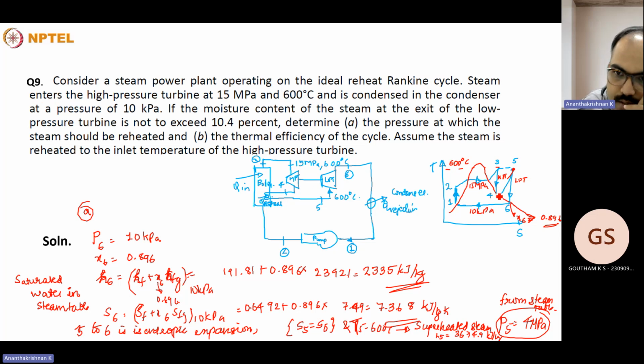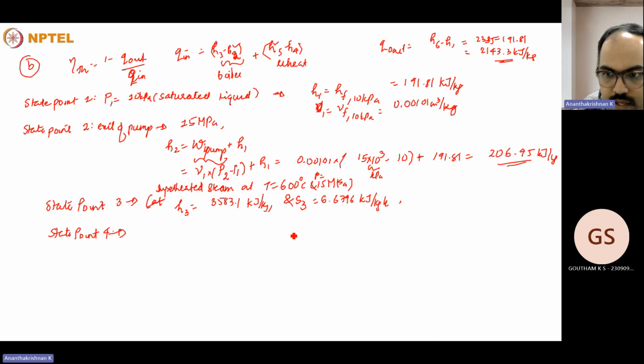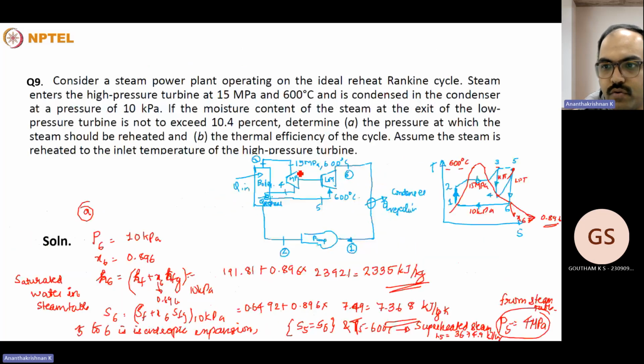So there are two particular cases. Take the case when it is superheated and try to calculate the enthalpy that you get corresponding to the entropy as well as the pressure. We know the pressure of this process: it will be 4 megapascal, which you obtain from the first part of the problem. And we have an entropy, so correspondingly we need to calculate the enthalpy.